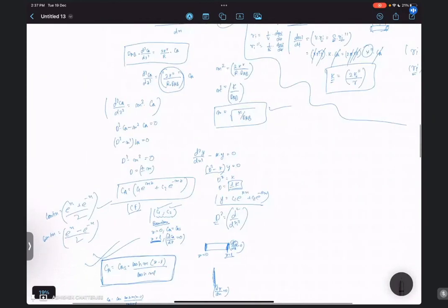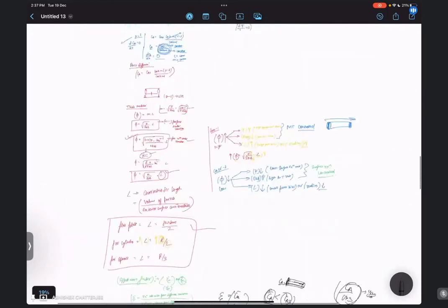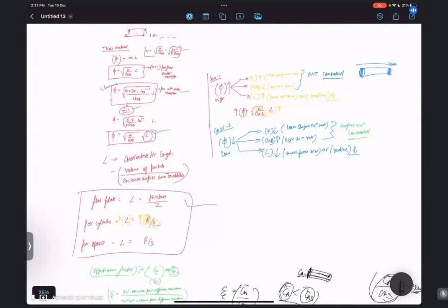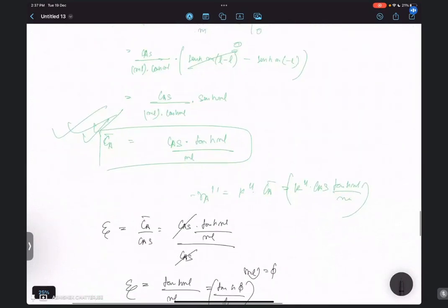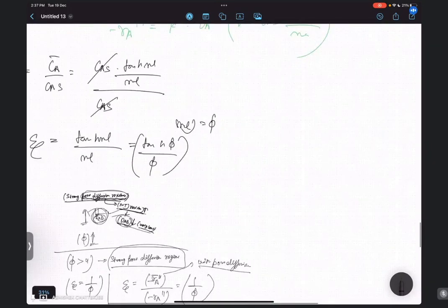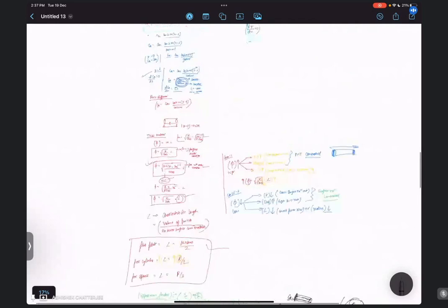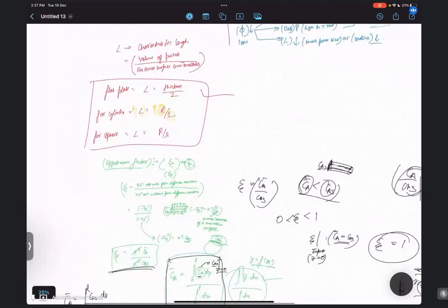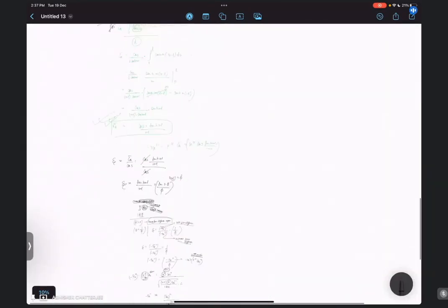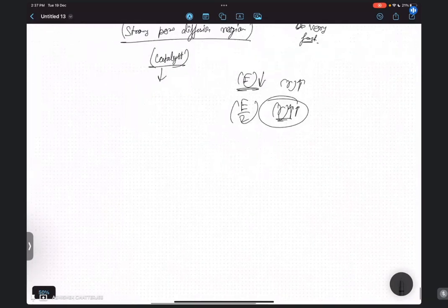For the cylindrical pore, you have derived this effectiveness factor, no? कहाँ गया cylindrical pore, कहाँ गया भाई? Yeah, for the cylindrical pore we have written the formula of your effectiveness factor, that is equal to tanh φ by φ. So for the spherical pore, what will be the effectiveness factor? That we will be writing down. Then suppose this Ca and Cas relation, we have seen it for a cylindrical pore. If it's a spherical pore, what will be the relation between Ca and Cas? That we will see. And some little bit of things I will tell you for solving numericals.